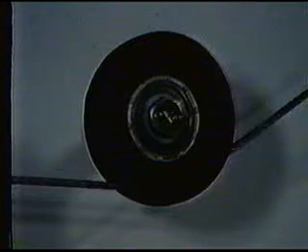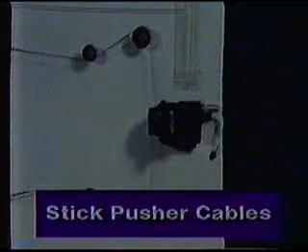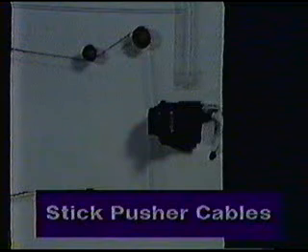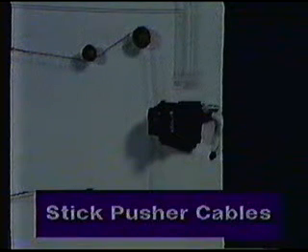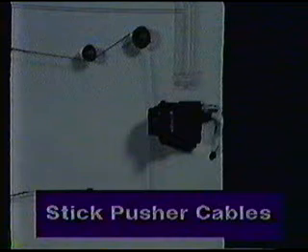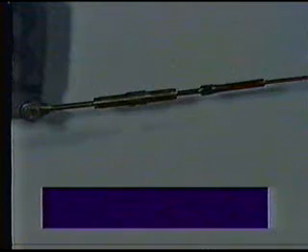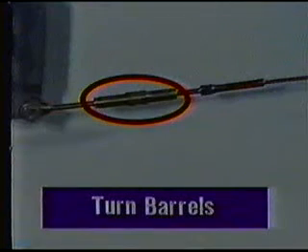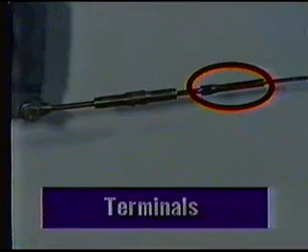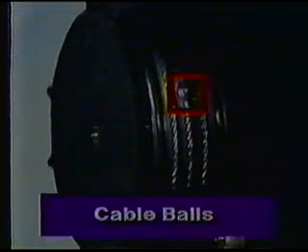Flight control cables are usually referred to by the surface they are attached to, such as rudder cable, elevator cable, aileron trim cable, and so on. The exception are the cables that connect the SAS servo to the control column, which are usually referred to as stick pusher cables. The fittings used in the control cable system all follow standard aircraft terminology, such as turn barrels, terminals, and cable balls. All fittings used in the flight control system are swage type attachment.